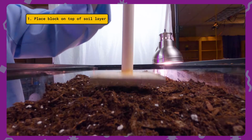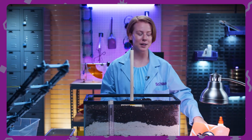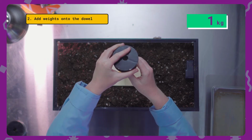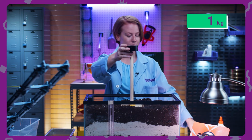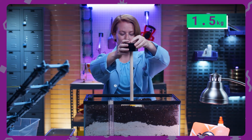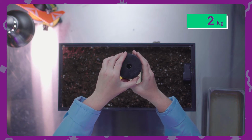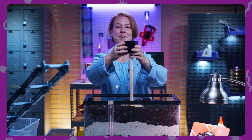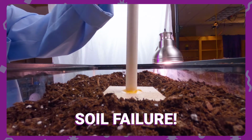So by holding the dowel ends, place the wood directly on top of the soil. Next up, grab your weights or your books. You're going to start to pile on the weights onto the dowel. At first we see that it's pretty stable, but as we load more on, the shallow foundation starts to sink into the soil and also become unstable. The soil fails when it's pushed out of the sides and slightly up around the block.